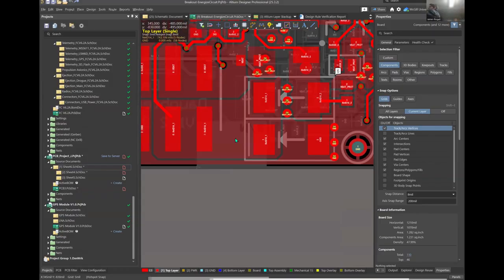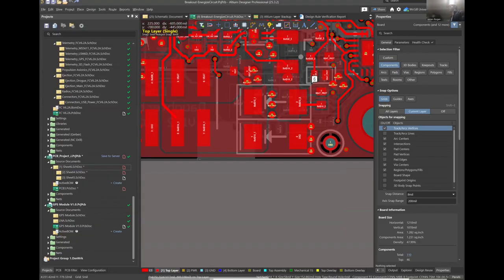In this case, I've set the opacity of the polygons to less, so that's why they're see-through. But you can see here that these pads are all connected, and this entire pour fills up with current, and that allows it to handle more than it would otherwise if I just routed a small trace.